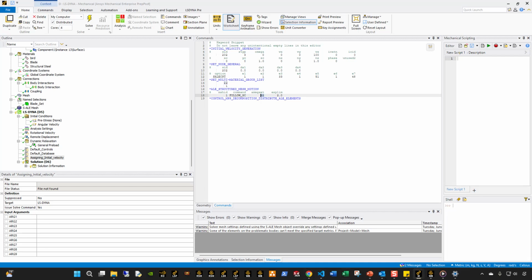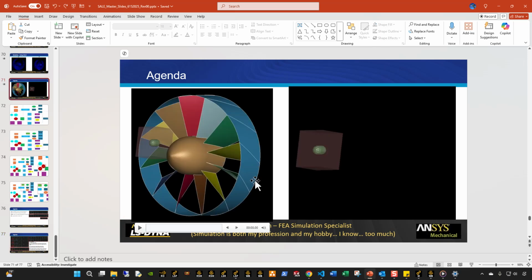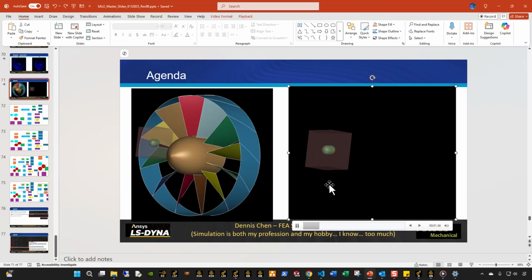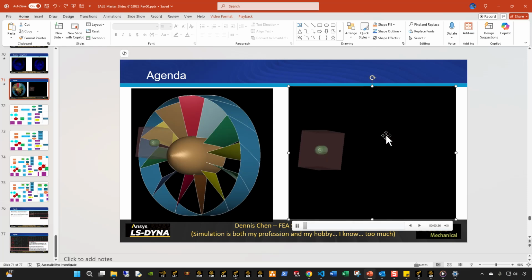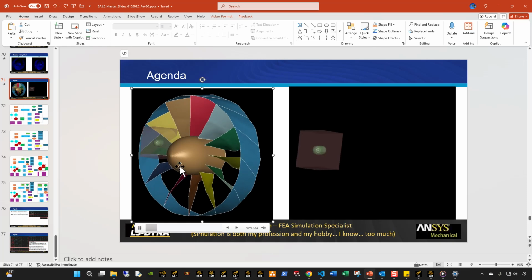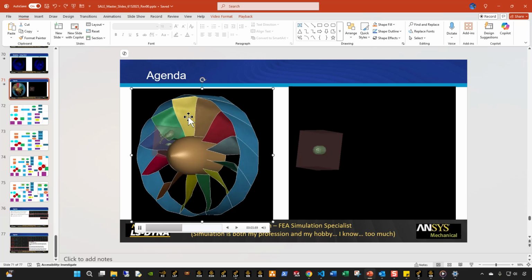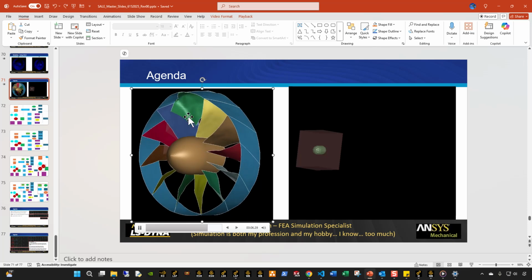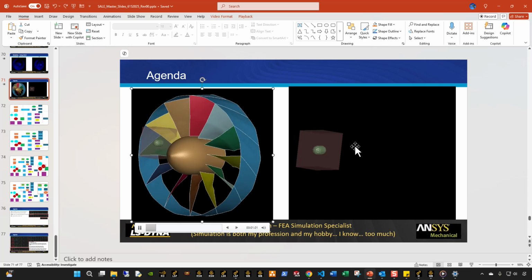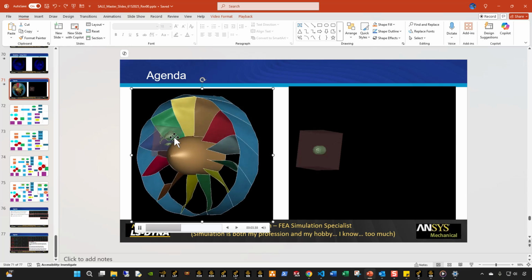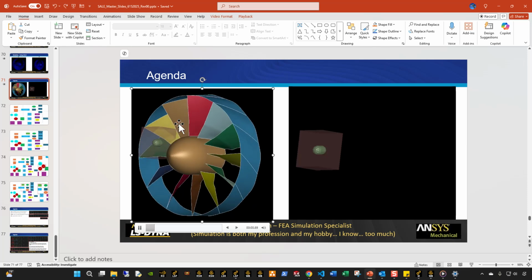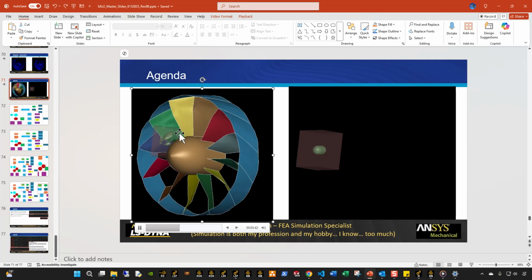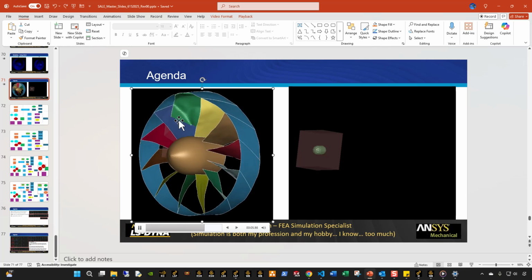And that's what you're seeing in the presentation here: it's able to stretch out because of that behavior. The reason this is necessary is that you can imagine the fluid body expands as soon as it hits the turbine blade. That's why we need to capture the stretching of the background mesh, to capture how much the fluid is moving. I actually didn't stretch it enough. You can see it disappears as soon as it hits right here, when in reality it should be a much bigger background mesh, to fully capture the interactions as the water particles separate.